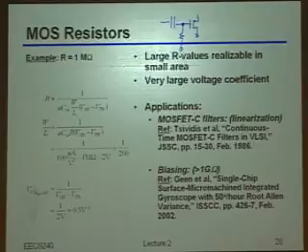The RC time. Yeah, okay, so first of all, the value of that resistance would set the RC time constant. And there, as an example, if the resistor was much bigger than it was supposed to be, what would happen? What was that? Yeah, basically, it's really actually the zero that would move to a lower frequency, right? Which means you'd be passing things at a lower frequency than you were before.